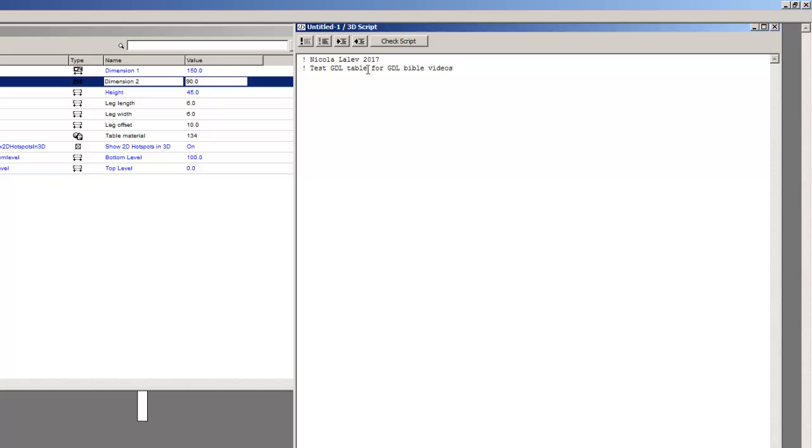And now we type the main section of our script as explained in the previous video, and we end that with the command end, and then we mark it. And below the end command are the subroutines. First subroutine will be to draw legs, and we will type gosub 1 draw legs. It's a comment, draw legs, and below it end, 1 return, and we will draw the legs.